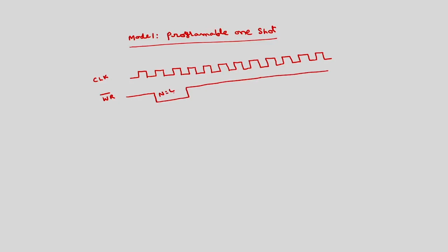Say n is equal to 4. Okay. For explanation purposes I am taking smaller values here. Otherwise this can be a 16 bit count, varying from 0000H to FFFFH. Now, an additional point here is, unlike mode 0 where the gate signal will always be high, here the gate signal is initially low. After write becomes high, the gate will go from low to high.